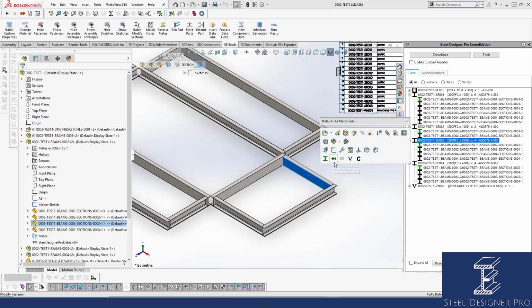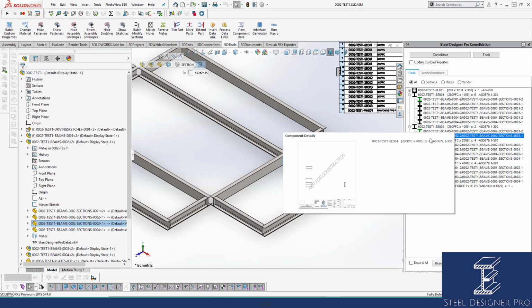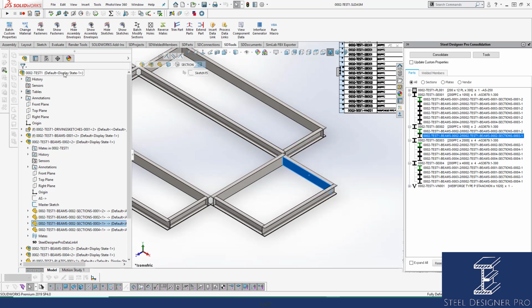So if I click on a face and then select consolidation, you can see that this is now section 2. It does that because it grabs the information based on the components in the tree and then sorts them, and then says these are the new marks that these items are going to get applied to. That's pretty much the basics of what can happen with consolidation. The reset marks will set it back up for you. However, just be mindful that if you do make a change, it may not be the required change that you're after. So you may need to reset your marks.